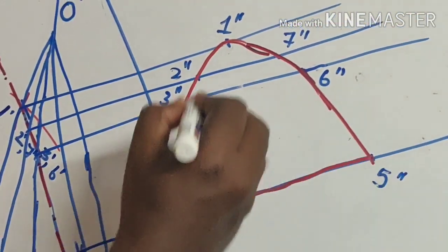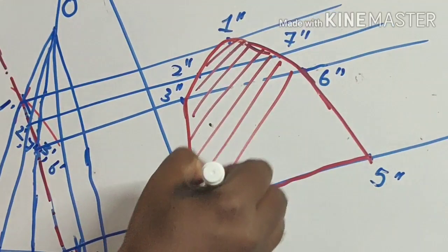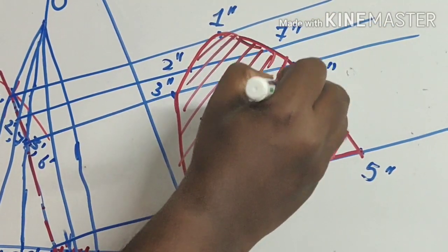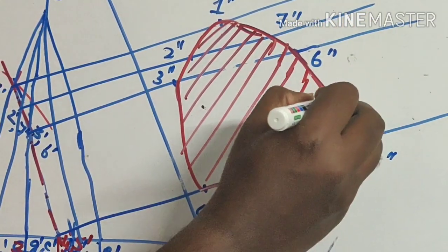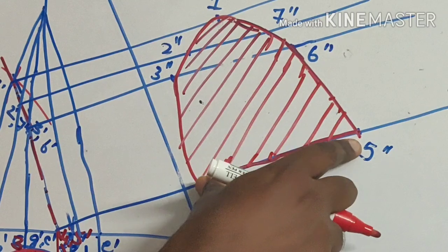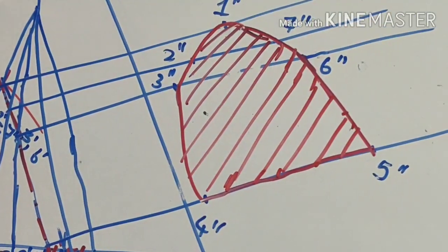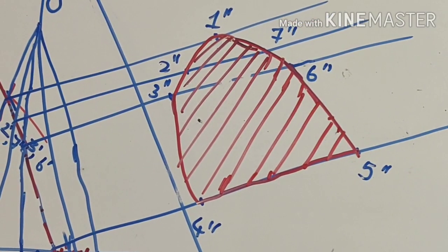You can close this contour, then you can hatch it. So now you got a parabola which is of double ordinate 50 and the length from vertex to the double ordinate as 50. This is what was asked in the question.